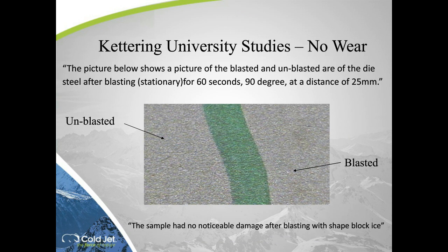I have all kinds of studies. I'll fly through this. We had studies done at Kettering University blasting standing still, just sitting stationary with dry ice at a 90-degree angle, 1 inch away, with no damage to the mold. That's not traditional blasting technique. For those of you out there that are familiar with it, there's always a traverse rate associated with it, but we did this stationary, in place for 60 seconds, still had no damage.